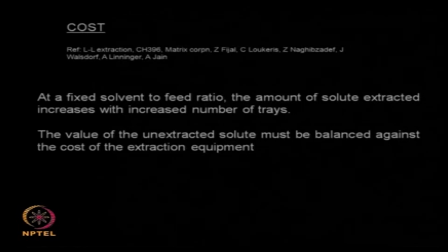Is it really worth extracting all the solute? It depends upon the price of the solute. Is it a very value added chemical or is it a bulk chemical? If I have a very cheap solute which I need to extract, there is no point in adding an extra stage or another extra liquid extraction system to extract as much as possible, because the cost of the equipment may be much higher than the amount that is being extracted.